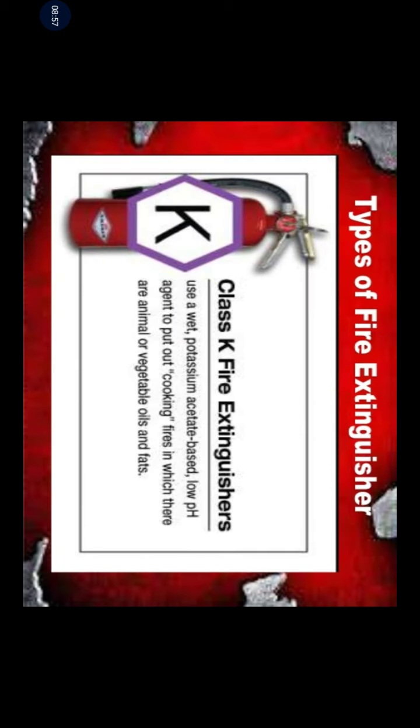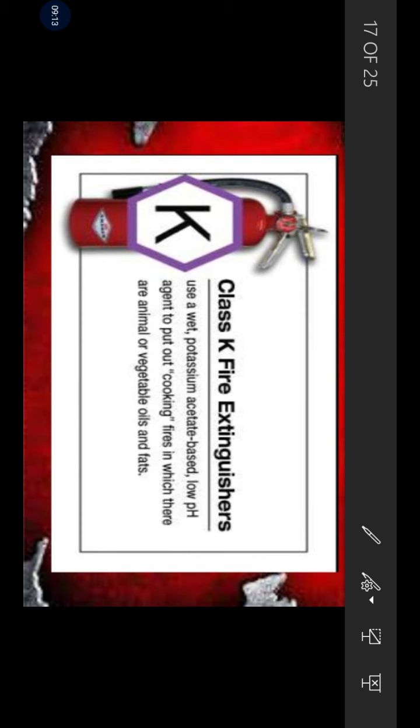The next one, class K fire extinguishers. Use a wet potassium acetate based low pH agent to put out cooking fires in which there are animal or vegetable oils and fats. Here we use a wet potassium acetate based agent. It has a low pH. It will extinguish cooking fires involving animal or vegetable oils and fats.